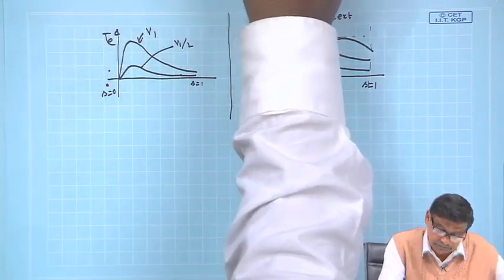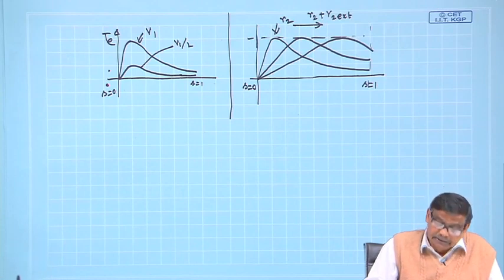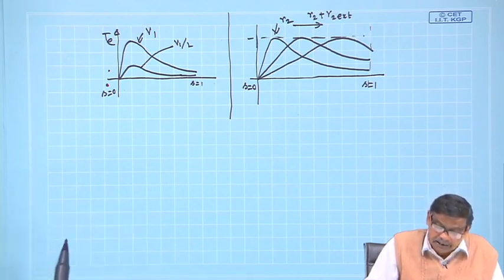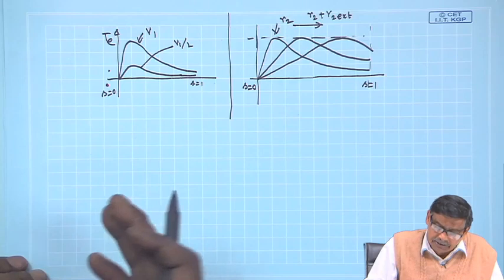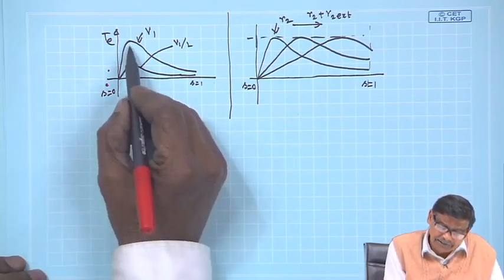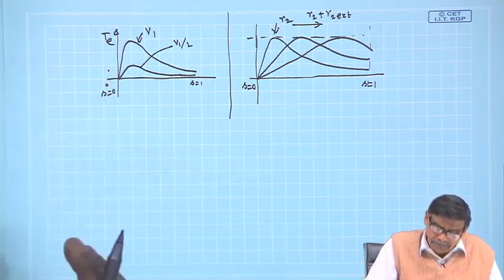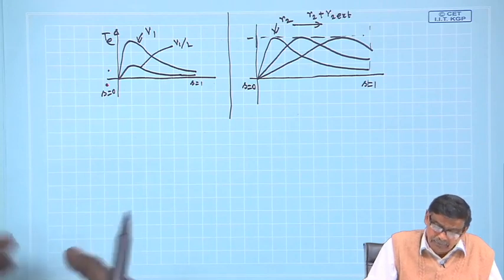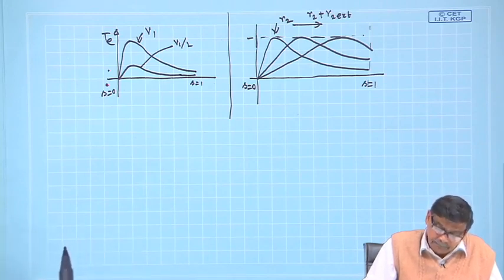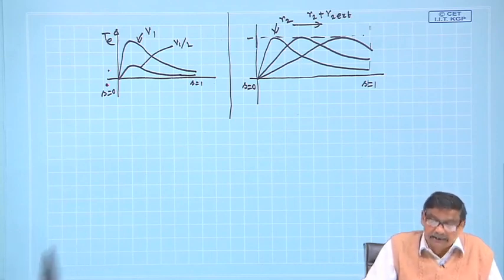We will solve several problems, we will give in the tutorial also. So, these are the two important variations that people generally make with induction motor, maybe reduce the supply voltage, which is not done very much, because you then sacrifice T max to a large extent, and therefore, it reduces the capability of the motor to supply any substantial meaningful load torque.